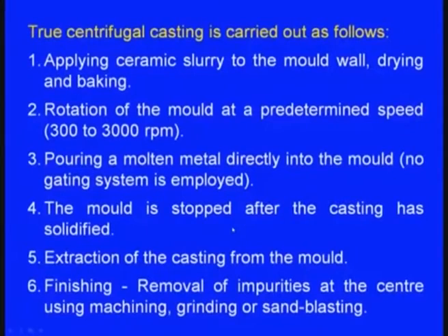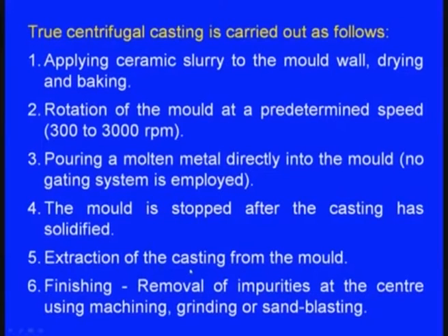The mold is stopped after the casting has solidified. Till that time the mold has to rotate. Then the next step is extraction of the casting from the mold, and the final step is the finishing. Means what is that? Removal of impurities at the center using machining, grinding or sandblasting.